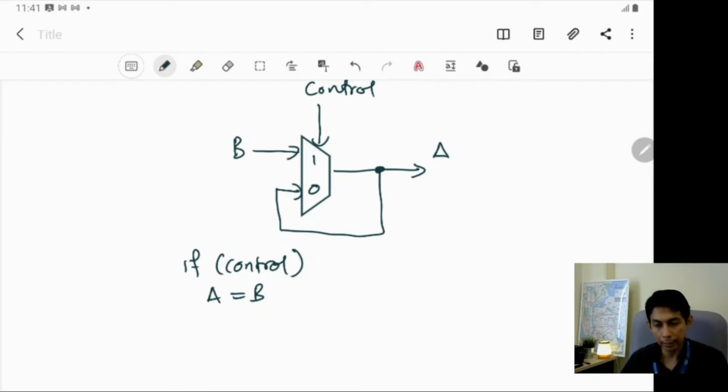So this is memory, or it will create the memory for you if you write the code like this. So in short, to create a memory, just write the code like this. Then you have the memory element, and this actually implements the latch. The D latch. The D latch behavior is like this. Okay. So that is how.